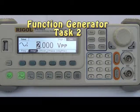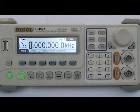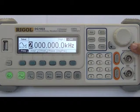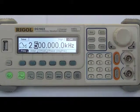Task 2 is to use the knob and direction keys to change the frequency. In order to get a value of 2.5 kHz, turn the knob to 2, press the direction key and tune it to 5. Once that is done, try to rotate the knob to change the frequency to 25 kHz.